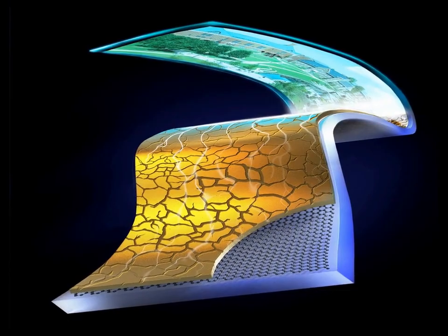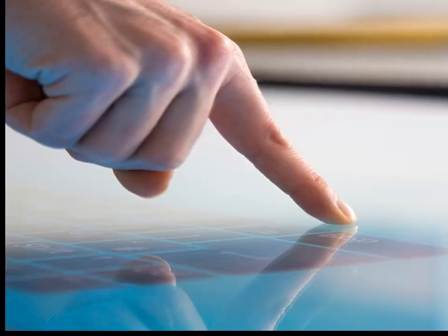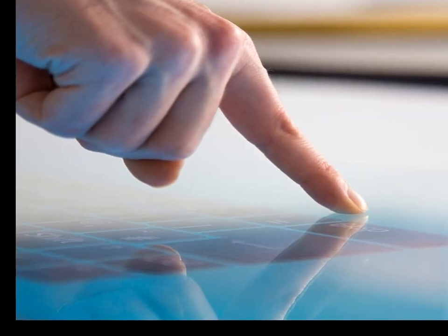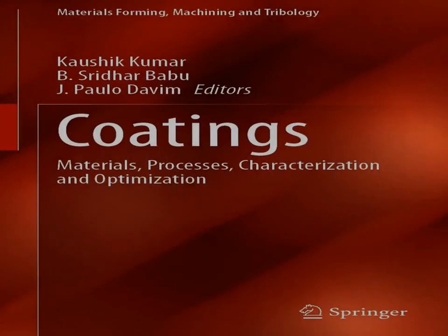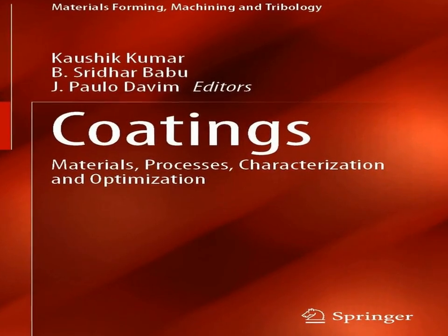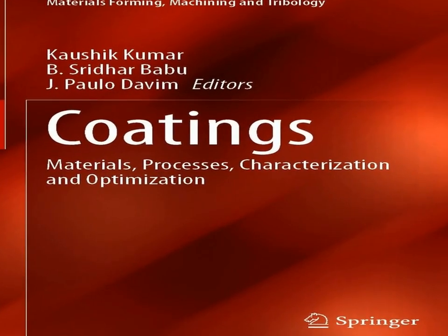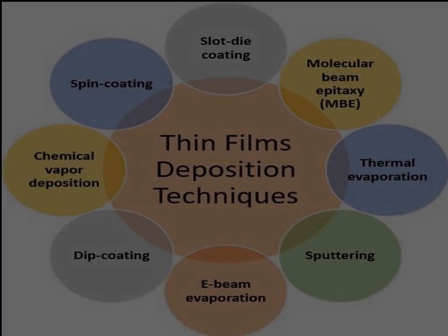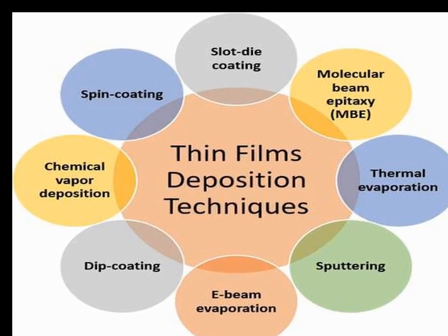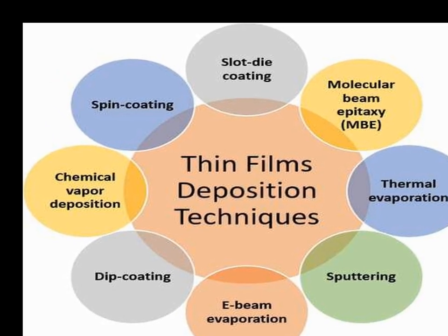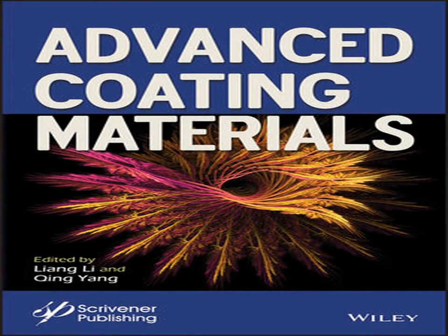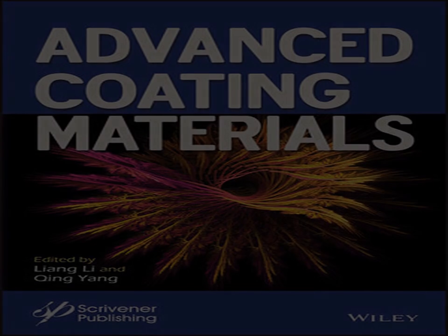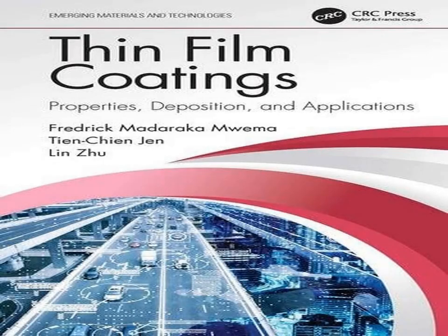Anti-reflection coatings on lenses and solar panels use combinations of oxides like CeO2, MgF2, Al2O3, and TiO2. Dielectric mirrors and optical filters rely on precisely engineered multi-layers. Transparent conductive oxides such as indium tin oxide and aluminum-doped zinc oxide combine transparency with conductivity for displays, touchscreens, and solar cells. Low emissivity coatings on architectural glass use nanometric silver films to minimize infrared heat loss.